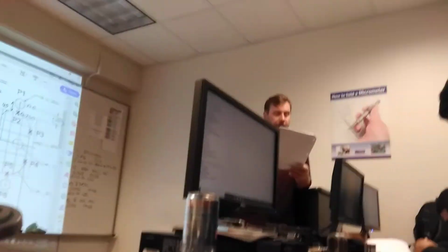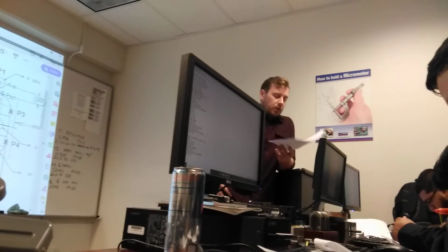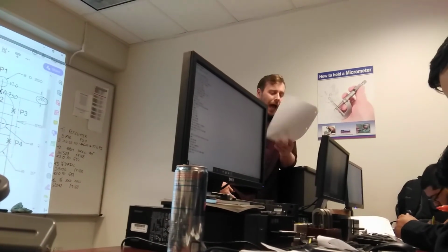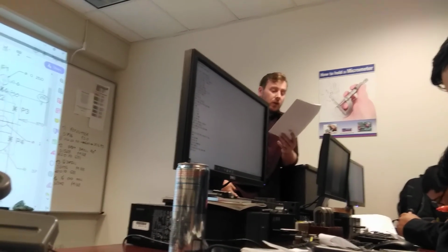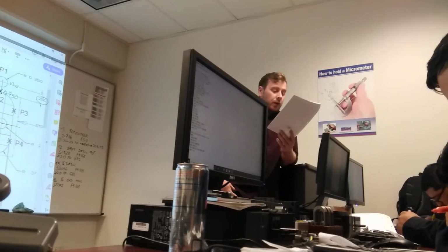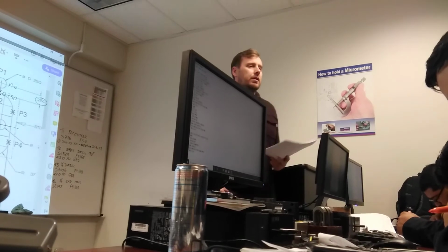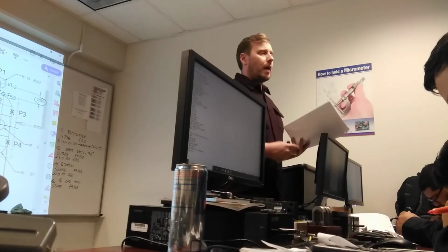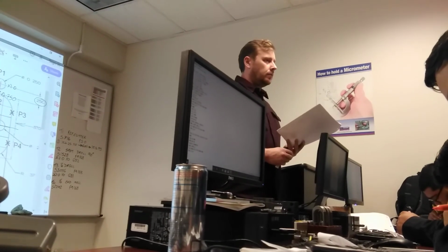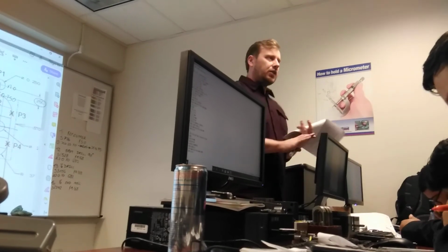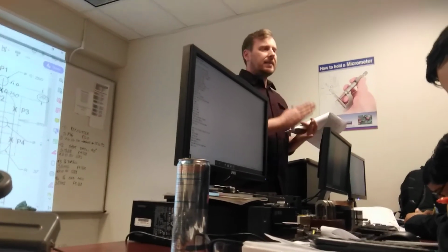Number 3, highlight the first sentence. When you make an X and or Y-axis move with G41, you need to tell the machine what diameter you want it to use. So you have to program a D. Whenever you activate G41, there has to be a D value.